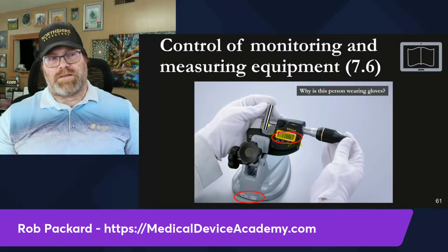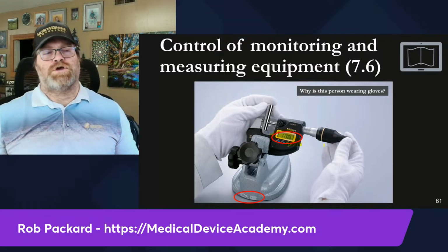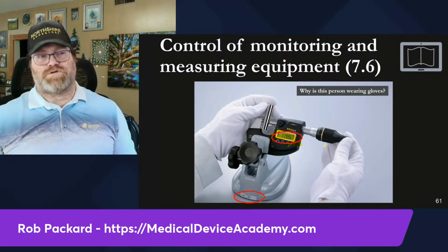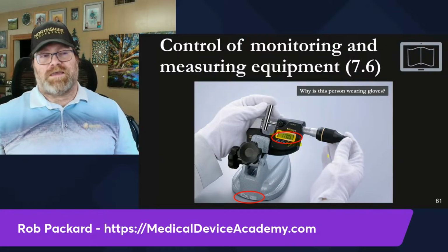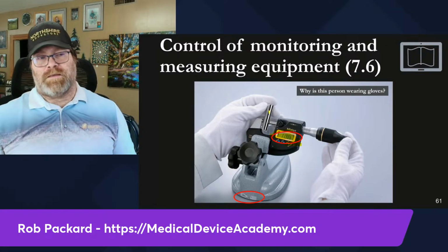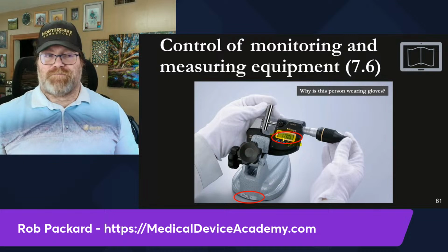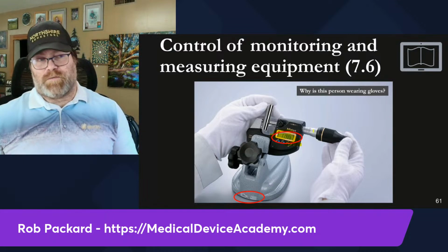So it's a 12 millimeter round gauge pin that's being measured, and it's 11.9 something. So the tolerance is plus or minus probably 0.02 millimeters or 0.03 millimeters, maybe even 0.05 millimeters is the tolerance on the drawing for that pin. But if you're doing crude measurements, that would be fine.